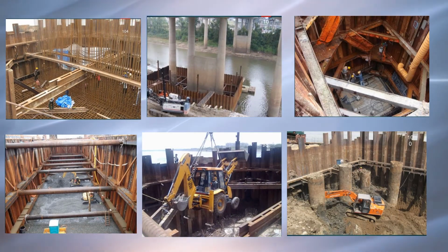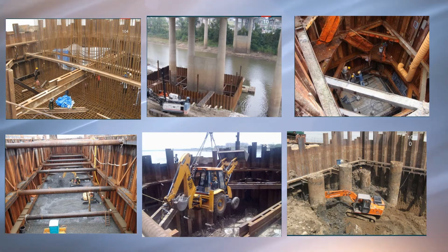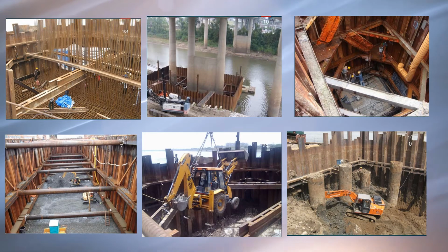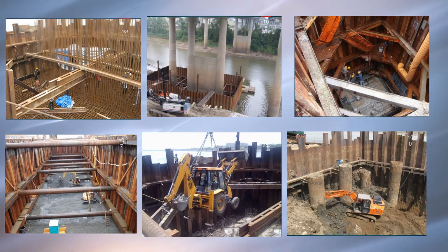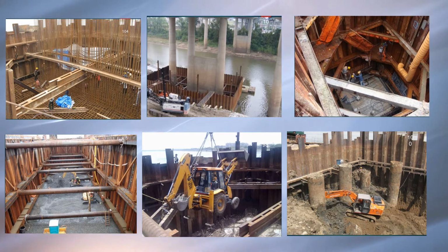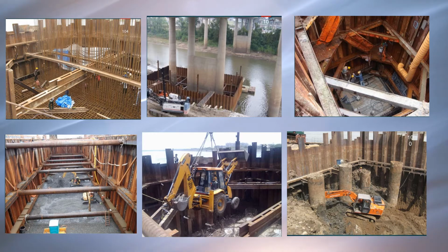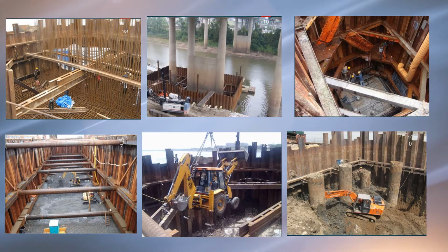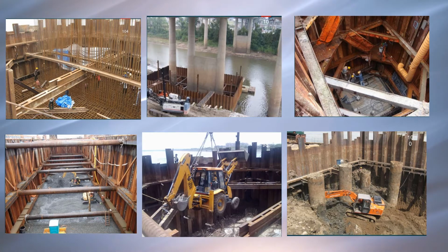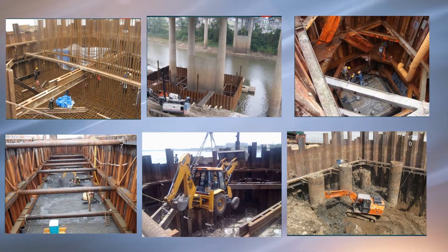The sheets on the two faces are braced by a truss arrangement of struts. This helps in increasing the stability of the walls against the water pressure. Half-filled bags of sand stacked on the inside and the outside faces of the sheets help in increasing the stability of the cofferdam. After the cofferdam is constructed, the water in the enclosed area is pumped out and the construction work is taken up.